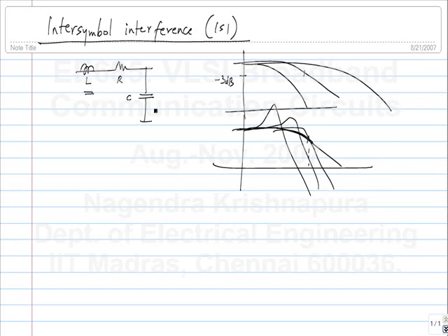So this is a series LCR network, the Q being 1 over R times square root of L by C. As L keeps increasing, the Q keeps increasing. But also the natural frequency, being 1 over square root LC, keeps falling. So this is what you will see. But there is one value of inductance where you can get the maximally flat response, or the Butterworth response. And you do use the trick in some cases to extend the bandwidth of RC. And this is a well-known thing.